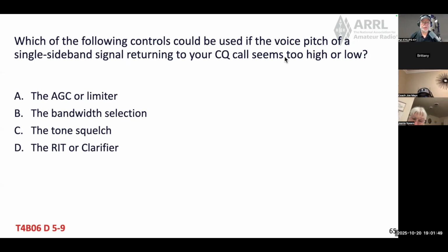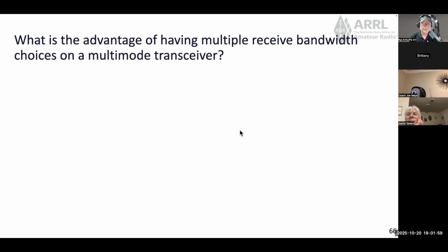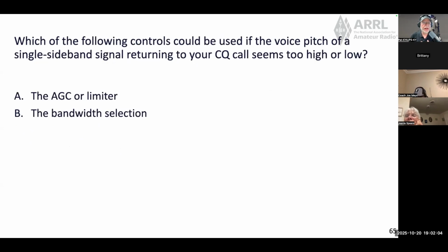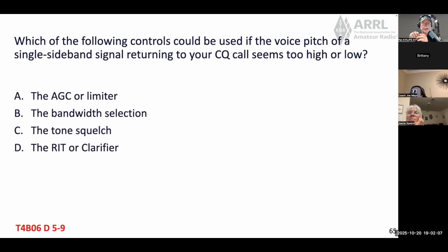So if you got a voice signal coming into you and it doesn't sound very well, you can use the RIT or clarifier control. Is that kind of like the volume on a handheld? Yes, it's like the volume, or it's like, not microscopic, but fine tune on the frequency of the signal that you're getting in. You can fine tune it, and that would help clarify so that you can understand what they're saying. Okay, thank you.